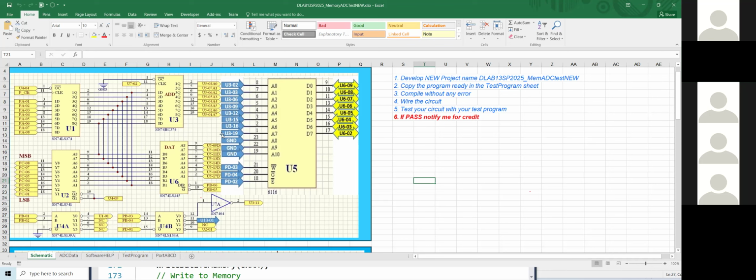That means after you already have the address ready and the data ready, now you want to write data to that location. So you set pin 21, 0, pin 21, pin 18, high, low, high. That completely writes the data to the memory.